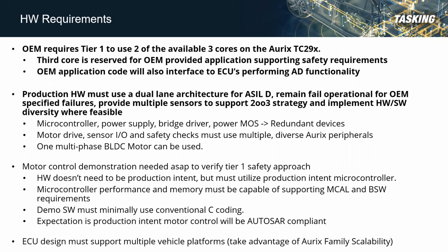So you basically have 2 copies of the same system next to one another. In the event, say, the safety ASIC fails in one of the 2 block diagrams, you have the safety ASIC in the other block diagram to ensure that you still have steering torque.